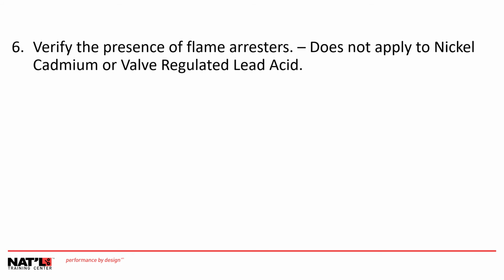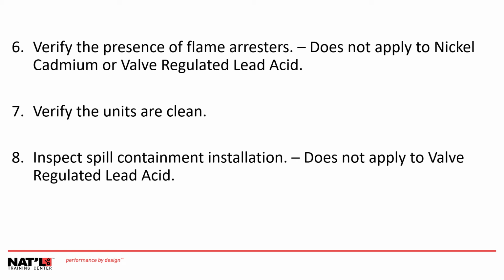Verify the presence of flame arresters. As with a few other things that we're going to be talking about as we move on with differences in types of batteries, the flame arresters do not apply to nickel cadmium or valve regulated acid batteries. Verify the units are clean. Inspect spill containment installation. This does not apply again to valve regulated lead acid batteries.